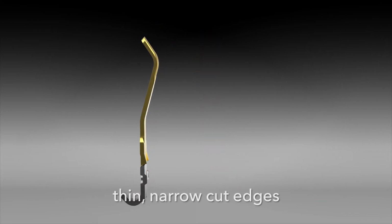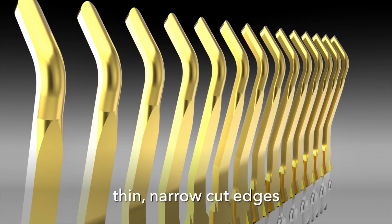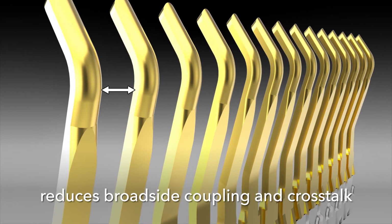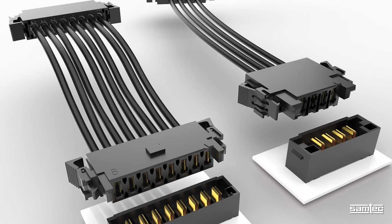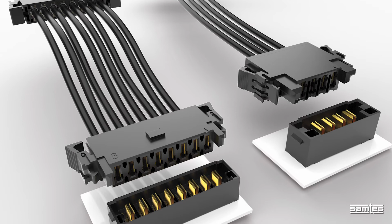The thin, narrow cut edges of the edge rate contact are positioned side by side. This minimizes the parallel surface areas, which reduces broadside coupling and crosstalk. Each type of contact will be tailored and modified based on the style of signal that you're sending. Features and benefits of the beam geometry will carry over, but will be larger or smaller based on power versus signal. Power is all about the cross-sectional area and how much energy can you pump through the contact system.